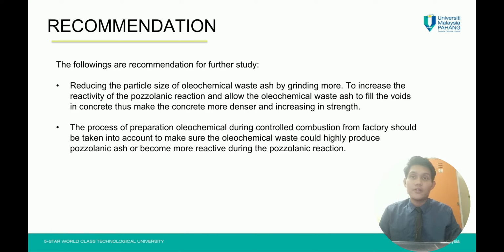So the recommendations for future study: first is reducing the particle size of the oleochemical waste ash by grinding more, to increase the reactivity of the pozzolanic reaction and allow the oleochemical waste ash to fill the voids in concrete, thus making the concrete denser and increasing its strength. Second, the process of preparing the oleochemical waste during controlled combustion at the factory should be taken into account, to make sure the oleochemical waste could produce highly pozzolanic ash or become more reactive during the pozzolanic reaction.